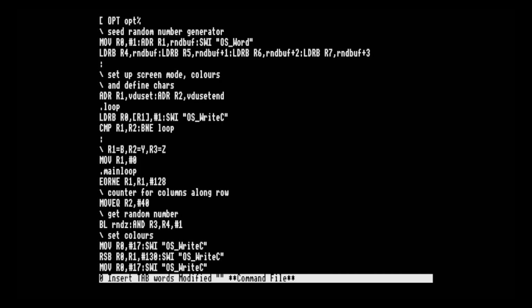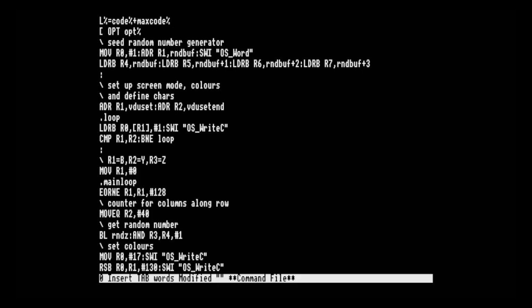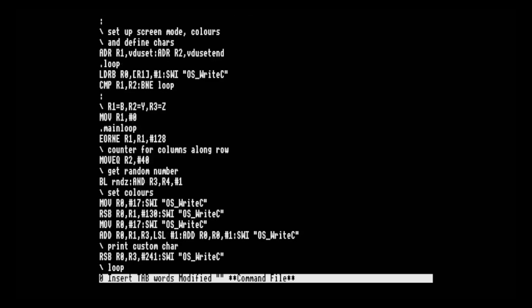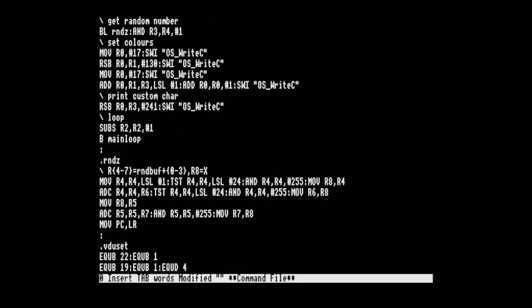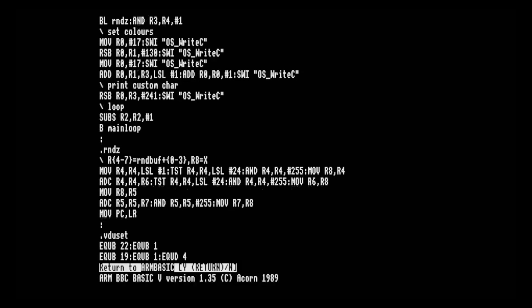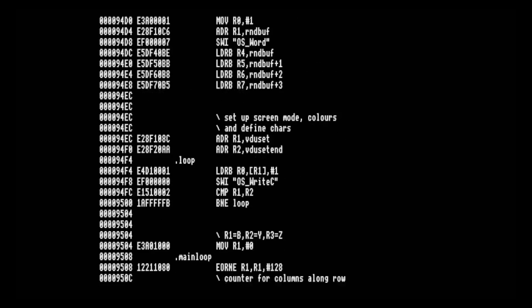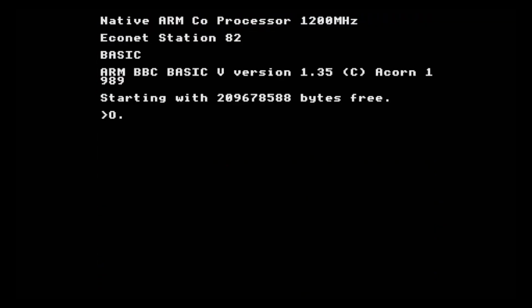I think I'm still down, but of course the really big thing with this code is that the extra instructions that I've had to add in are up here and executed only once, and we've removed an instruction from here as well in the middle. And probably more importantly, this subroutine now operates entirely using registers in the processor with no memory. So that speeds things up enormously because we don't need to keep reading and writing memory, which is much slower than the registers. So if we just save things out and run to assemble, call the code, and it all still works. So that's improved things.